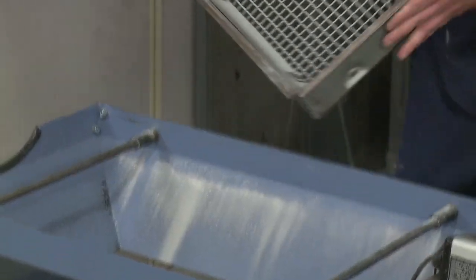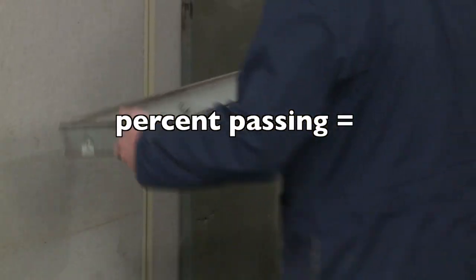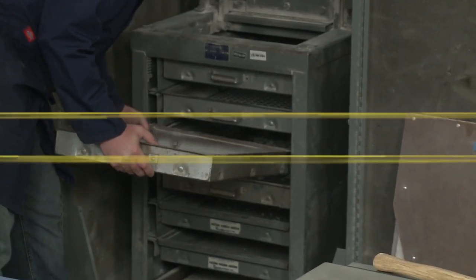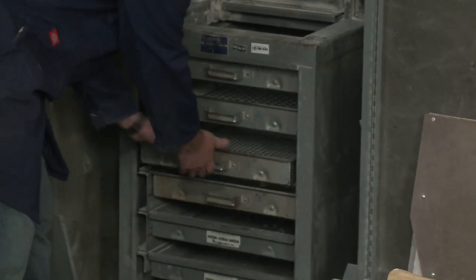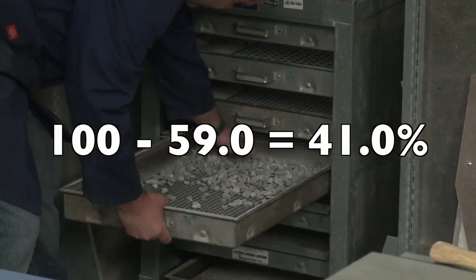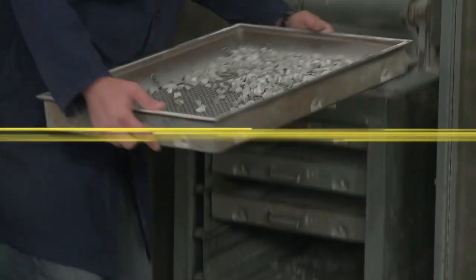To get the percentage passing the same sieve, simply subtract the percentage retained from 100. In this case, the percentage passing the half-inch sieve is 100 minus 59, which equals 41%.